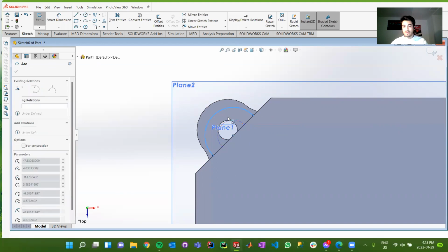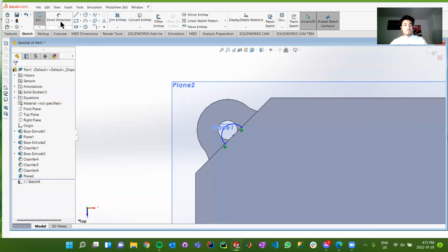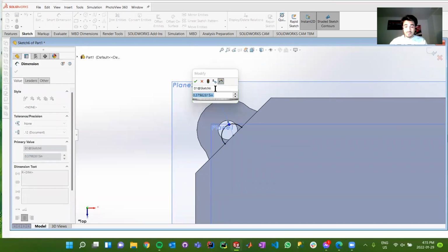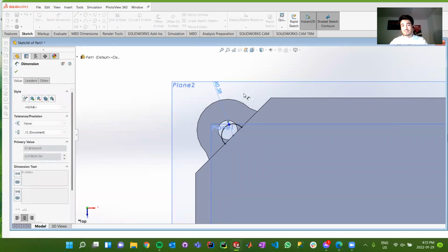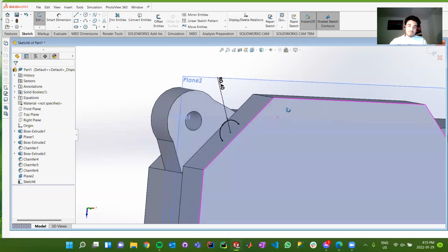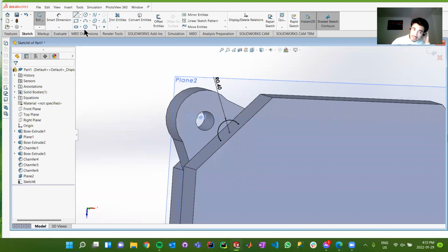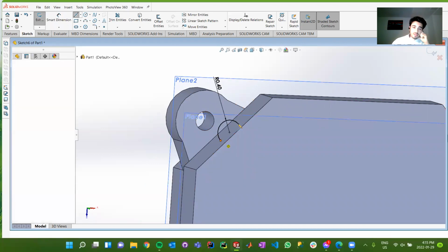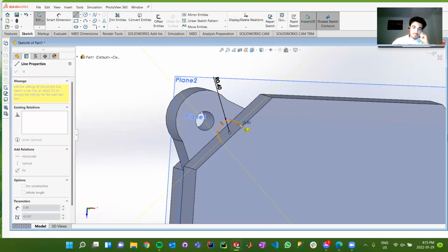So what we want this to have is a set radius such that it doesn't move around like you're seeing here, such that it can't expand or contract. I'm just going to give it a relatively small radius of, let's say, 0.4 inches. Flat. Perfect. And you'll notice it's perfectly centered. It's a bit difficult to see, but we have that. And then what we need to do is close the contour as well.